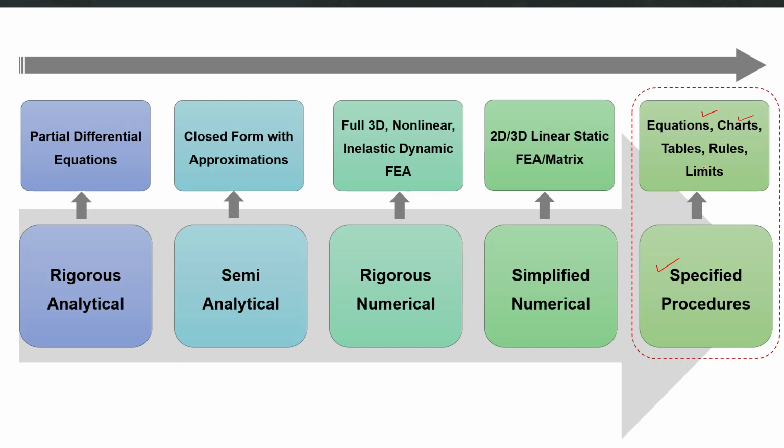I think with the advent of computing tools and latest technologies, now we can shift from these specified procedures to more explicit ones like 2D linear static finite element analysis, which are matrix based methods, or maybe to full three-dimensional nonlinear inelastic dynamic analysis, or the detailed nonlinear analysis of structures.